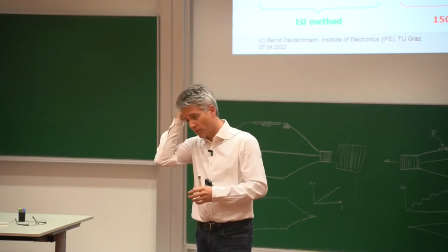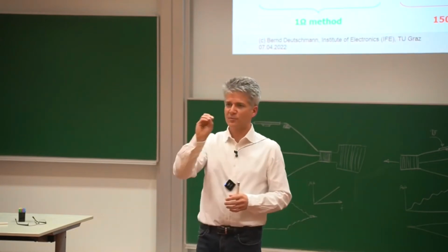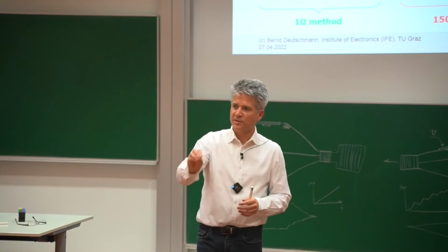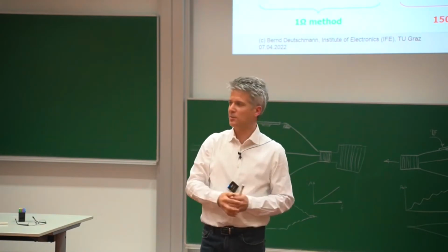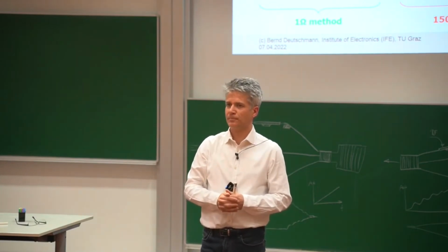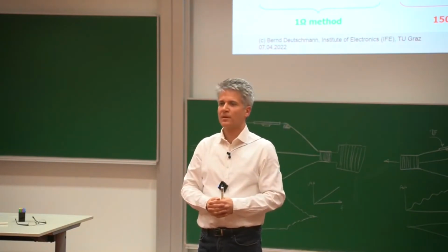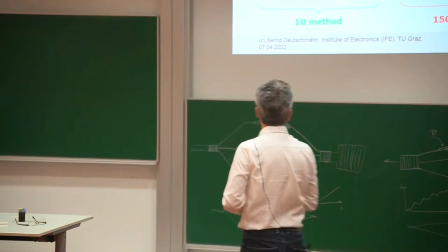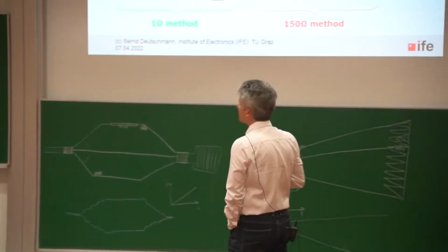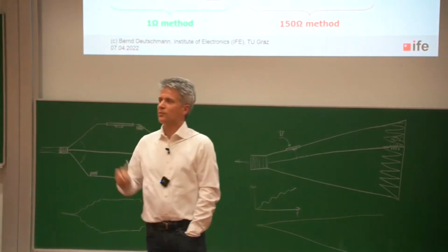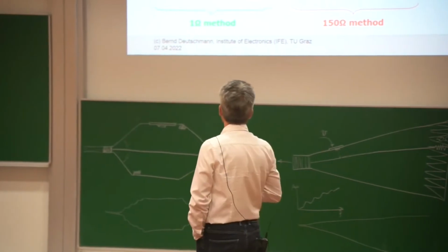And then they came to the idea, okay, then let's define a network consisting of passive components, which is exactly defining 150 ohm. And this network is then connected to the IC pin. They're just simple components. They can be placed in a very reproducible way, and then we can characterize the electromagnetic emission of the IC. And this was then realized in the so-called 150 ohm measurement technique, where they are placing really a 150 ohm antenna impedance at the pin of an IC.